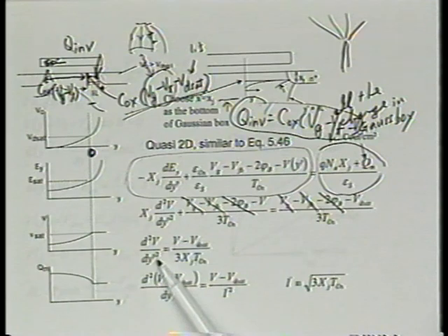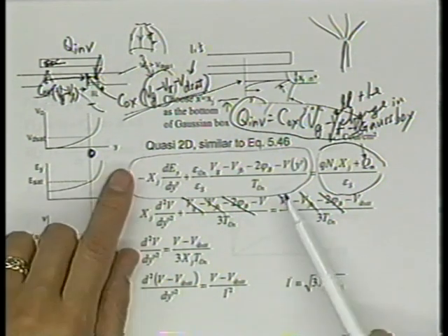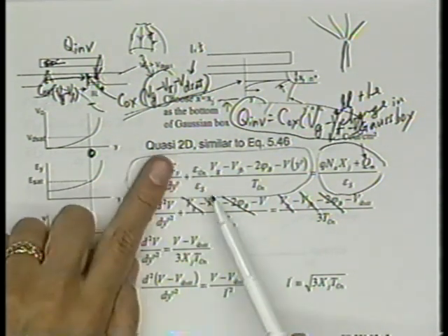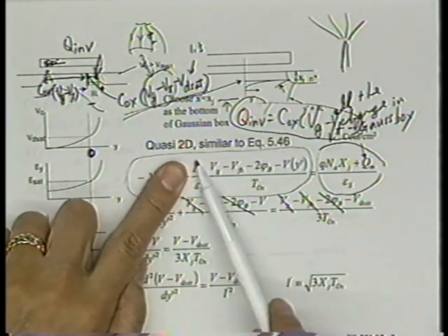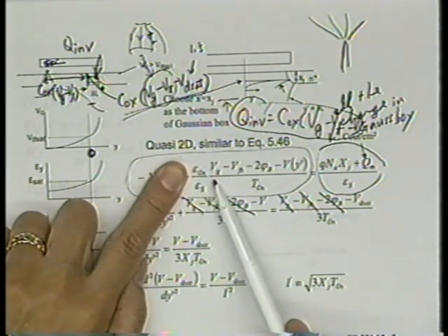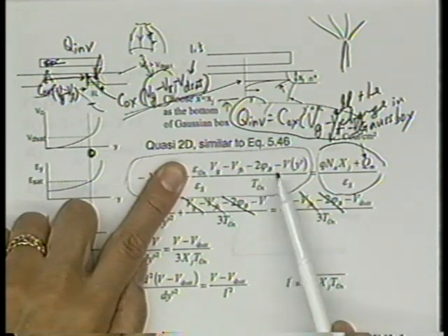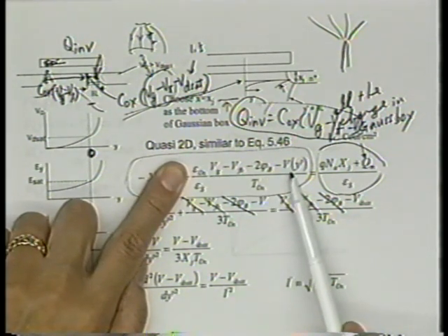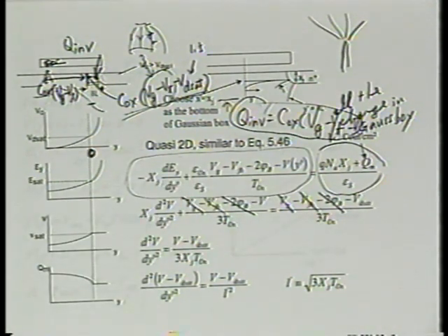But it's a very clever way to get rid of the qm. It's by evaluating this at y prime equal to 0. At that point, this term is negligible. So we just replace this qm whole term on the right-hand side with this at y prime equal to 0. At y prime equal to 0, this term is all known. Vg is known, VFB is known, 2 phi b is 2 phi b. This is Vd set. So we replace the right-hand side with that. Okay?